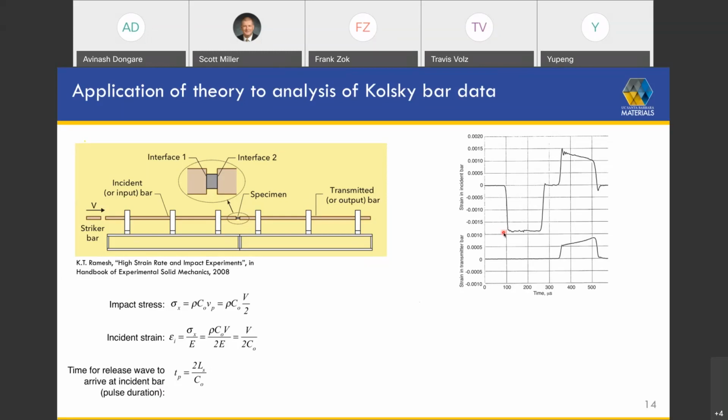Then there's a temperature regime and a strain rate regime over which that sensitivity is lost for a number of reasons. For example, if you have an FCC material, the intrinsic lattice resistance is small, and the barriers to dislocation motion, the thing that makes FCC material strong, are things like dispersoids or precipitates. These are long-range types of obstacles, and it's difficult for dislocations to bypass those obstacles through thermal energy.